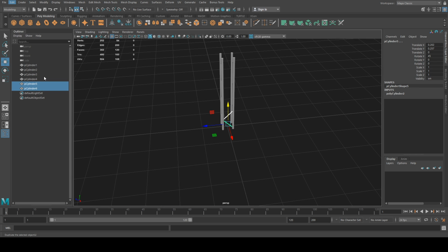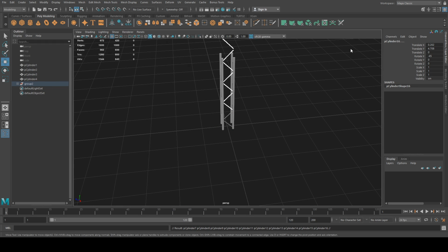So I've now put those two on 45 degrees. I'm going to duplicate them. I'm actually going to group them and then duplicate. We'll move it up to 0.8. So I'm going to go edit, duplicate special, and I'm going to translate them by 0.8, 1, no rotation, and let's give myself 5 copies. Cool.